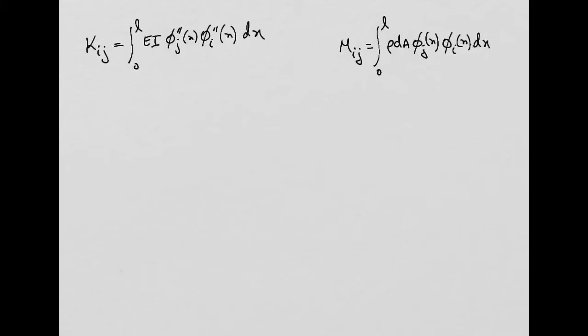Right. So for the shape functions, we are going to start defining. The strategy is, for these shape functions phi, you can use the same functions we used last week, those involving sines and hyperbolic sines, cosines and hyperbolic cosines. But I'm going to do it in a different way. I'm going to use polynomial functions, but I'm going to start defining not the functions phi, but the second derivatives.